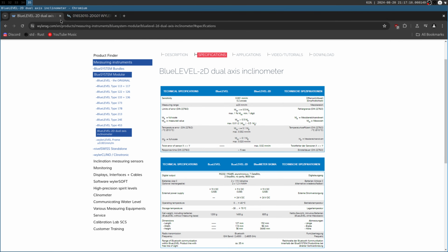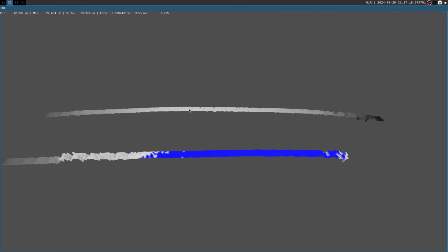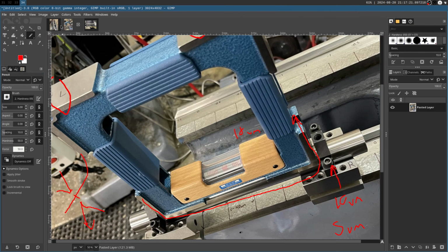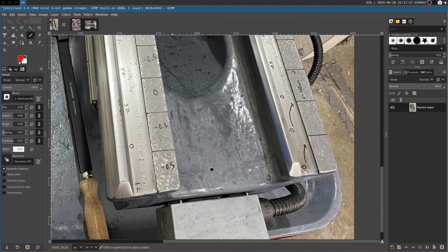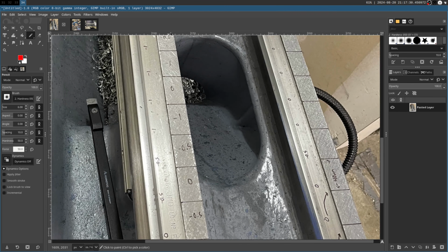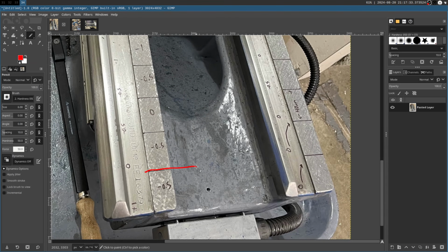Okay. So anyways, what I'm trying to do is I have that dumbbell set up, and then I take that dumbbell and run it down the lathe bed, right now every 40 millimeters, every 4 centimeters. So what I've done is I've taken a tape measure down the lathe bed and marked a line at every 40 millimeters, and you can see that on both sides. I try to line these up as close as possible, but it doesn't really matter if they're not perfect, because if this sets a little bit at a diagonal, as long as it's consistently diagonal, it's the same information, right? So even though this is kind of eyeballed, whatever.